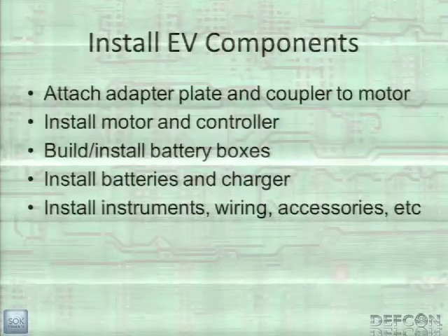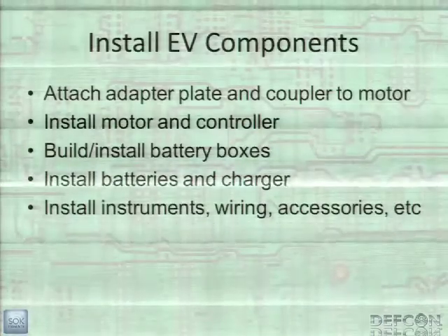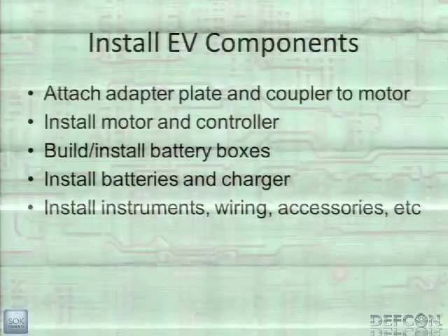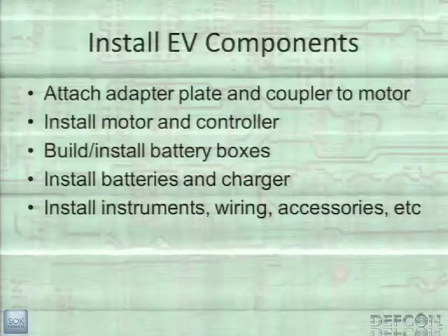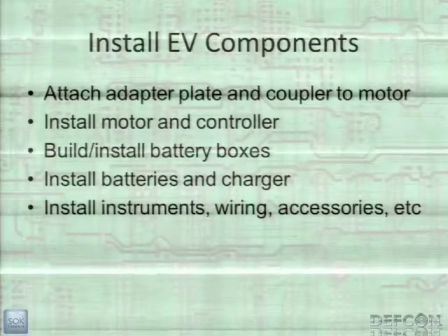Once you have everything, it's pretty straightforward. With the Bug, it's just 4 bolts to put the motor on once you get it lined up properly. Install your motor and controller. You need to build and install your battery boxes. That's probably the hardest part, building battery boxes.